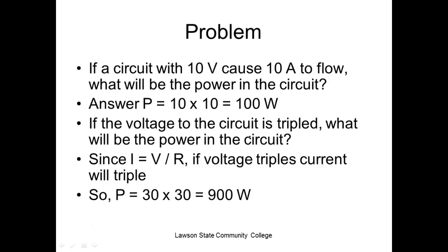So instead of getting 120 volts, it gets what? I think the relay resistance is like 1,000 ohms, and so if they were 1,000 ohms, then it would get 1/3 of the voltage, right? You understand that? So it would get 1/9 of its power. Y'all understand that? And so if it's a 25 watt light bulb, and you divide that by 9, right? The light doesn't even come on. And they say, well, something's wrong with this light bulb. It doesn't come on. I keep telling them, it's not getting enough voltage to produce that power.